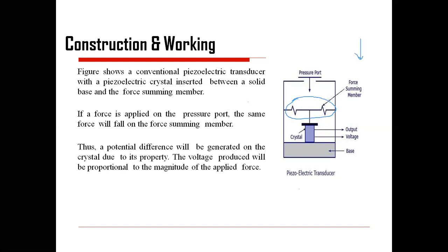When we apply the pressure on the diaphragm, that diaphragm will automatically provide you displacement. And below that diaphragm, one stick or one hard pointer is arranged, below which the piezoelectric crystal is mounted. And below that, here is the base. Now, what is happening with this? When we apply a pressure or a force on this, it will try to deflect or generate a displacement over here.